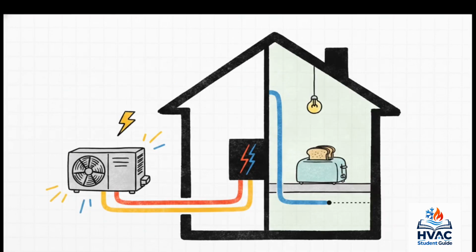When that power finally makes it to a typical home, it arrives as a 120/240 volt service. This is your standard single-phase 60 Hz 3-wire system. It provides 2 ungrounded hot conductors that give you 240 volts for your heavy, large loads. Think the home's main air conditioning equipment or the electric range. Then, there's a grounded center tap neutral that allows you to pull 120 volts from either hot wire to safely run all the smaller appliances and control circuits around the house.